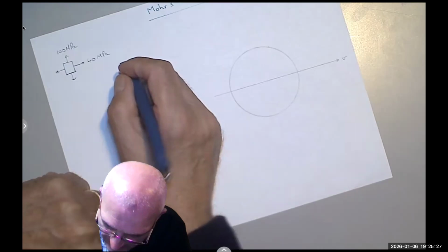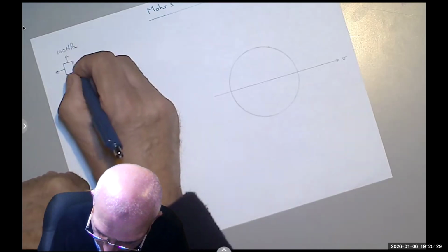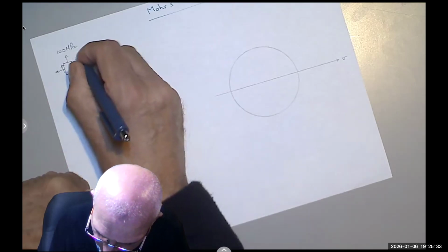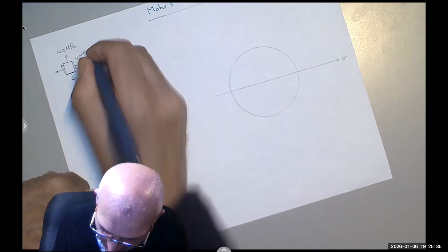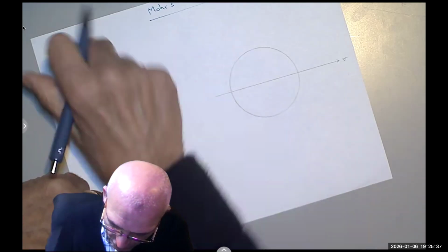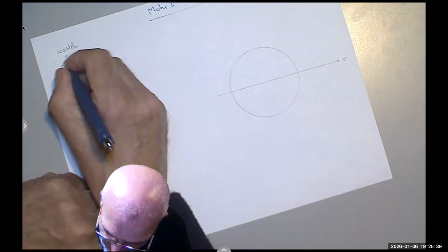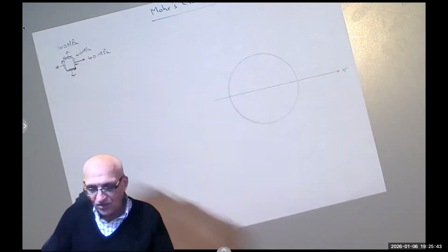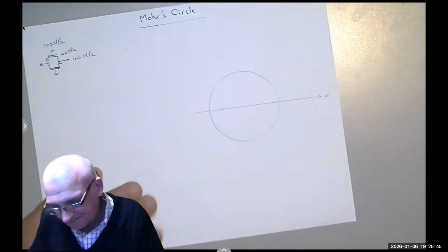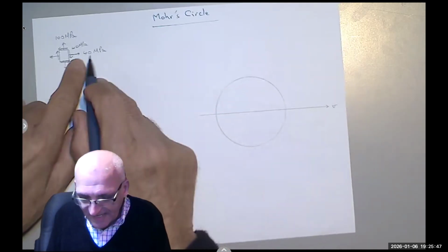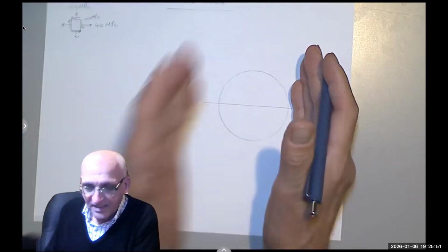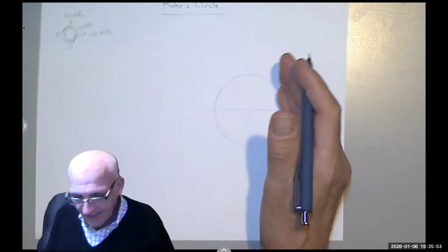And let's say the shear is 40 megapascal also going like that. And if these are rotating clockwise, so on the other face, they should be rotating counterclockwise to counter their effect, and all of them are 40 megapascal. So the x is 40, the y is 100. So the y would be to the right, the x would be to the left, okay?